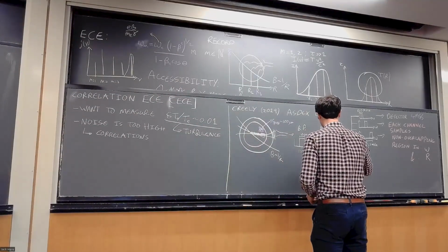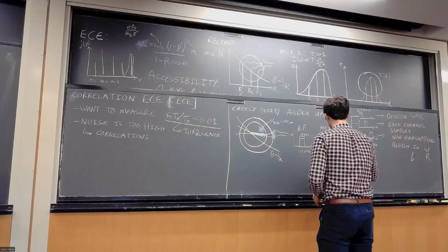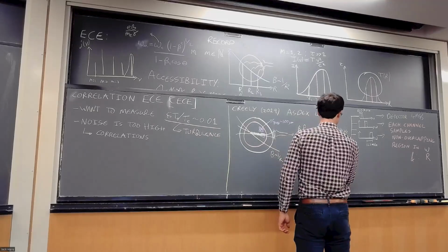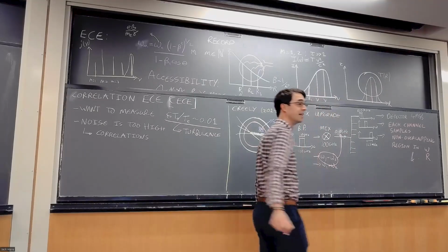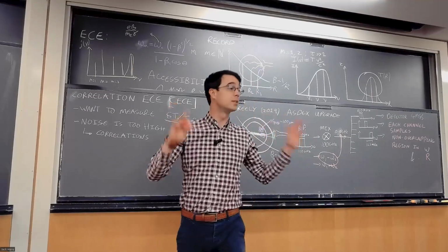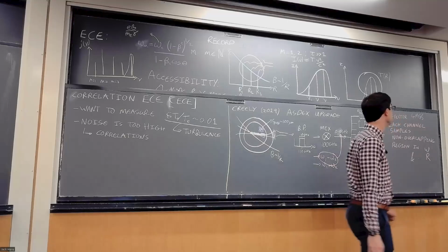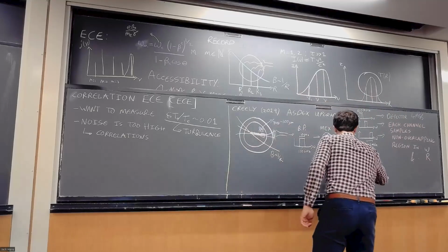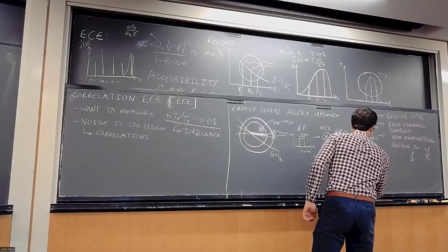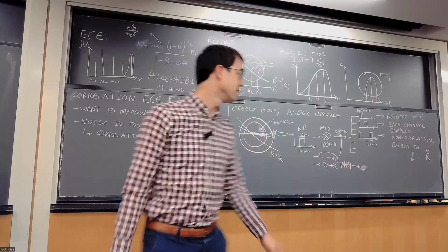We get out a frequency at omega 1 minus omega 2, and a frequency at omega 1 plus omega 2. Omega 1 minus omega 2, that signal is about 0 to 10 gigahertz. We can digitize that. This one, whatever, 200 gigahertz, we still can't. On the integration time of our detector, the sampling time, that will have many, many oscillations, and because it's power, it will average out to like 1 or something like that. So it's some DC offset that we can subtract off after.